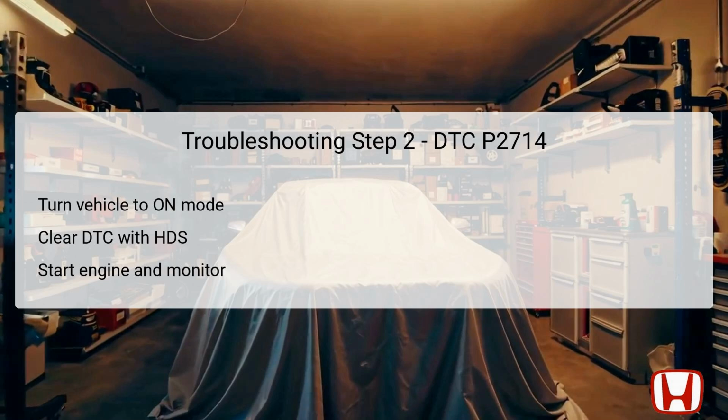In troubleshooting step 2, turn the vehicle ignition to the on position, engaging the accessory mode without starting the engine. This allows the technician to use the Honda Diagnostic System, HDS, to clear the DTC from the system. Once the DTC has been cleared, start the engine while pressing the brake pedal and shift the transmission into the D position. During this process, it is critical to monitor the OBD, onboard diagnostic, status for DTC P2714 through the